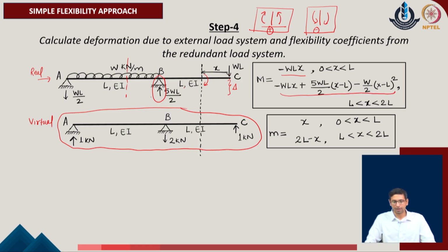We have identified these support reactions by solving a simple statically determinate problem first, and that is why the reactions 5WL/2 or WL/2, these are the set of reactions which are known to the user by solving the determinate system of the given problem.